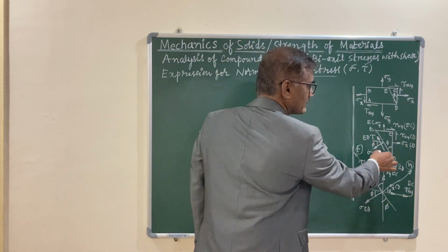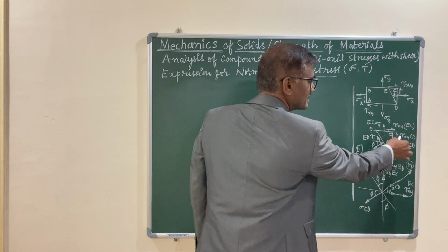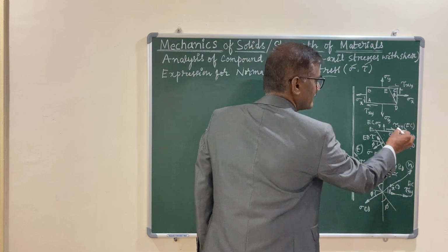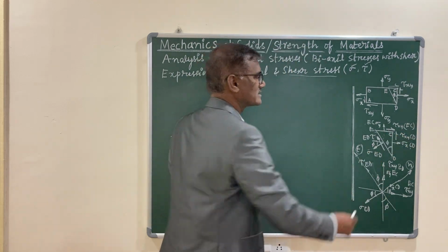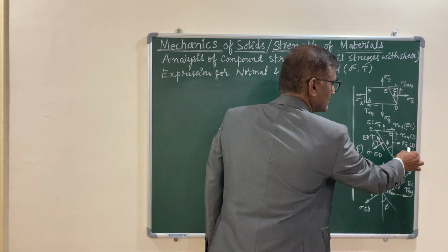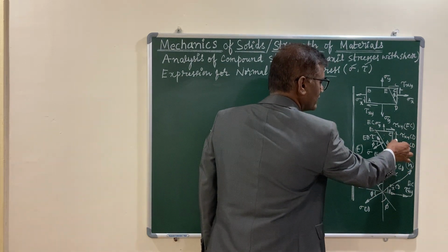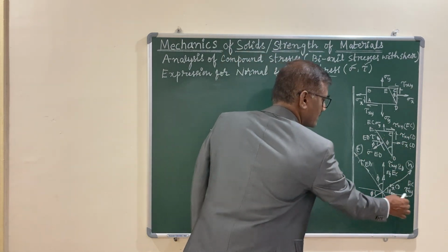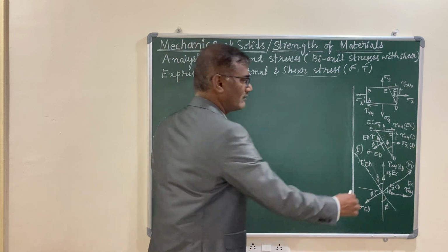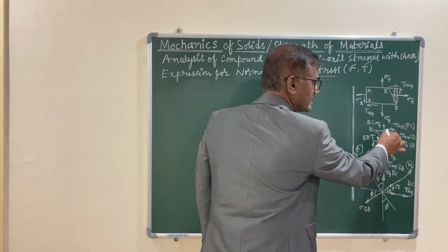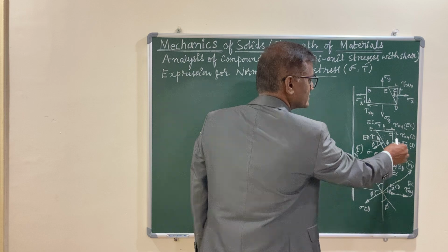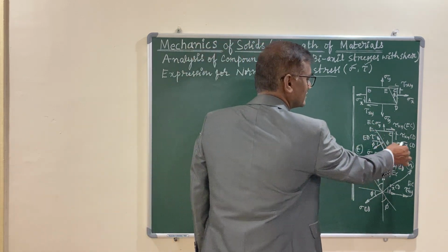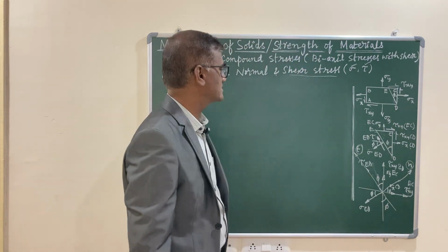And I am converting the stresses, multiplying with appropriate areas, as forces. And I am assuming the thickness is unit thickness. So let us multiply with the appropriate areas to convert to forces, and all these forces are represented on coordinate axes along x and y direction. Now, this particular element is in equilibrium under the action of the forces, which you have converted from stresses by multiplying with the appropriate areas.